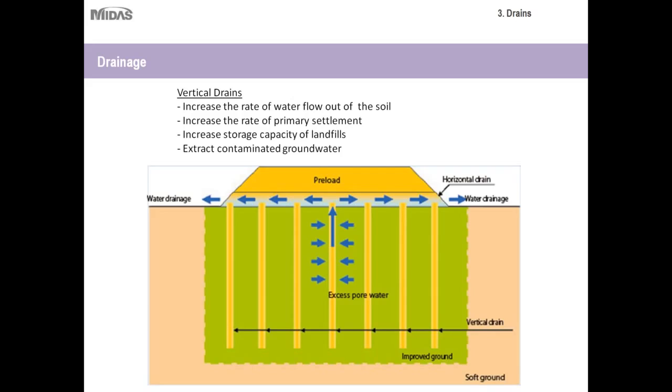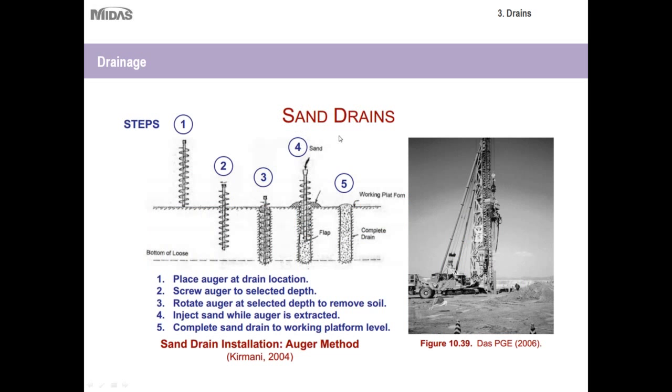So, consolidation of soft cohesive soils using prefabricated vertical drains. We'll talk about PVDs, or prefabricated vertical drains, in more detail. But there are also sand drains, which are used to drain the soil out as well. So let's talk about sand drains.